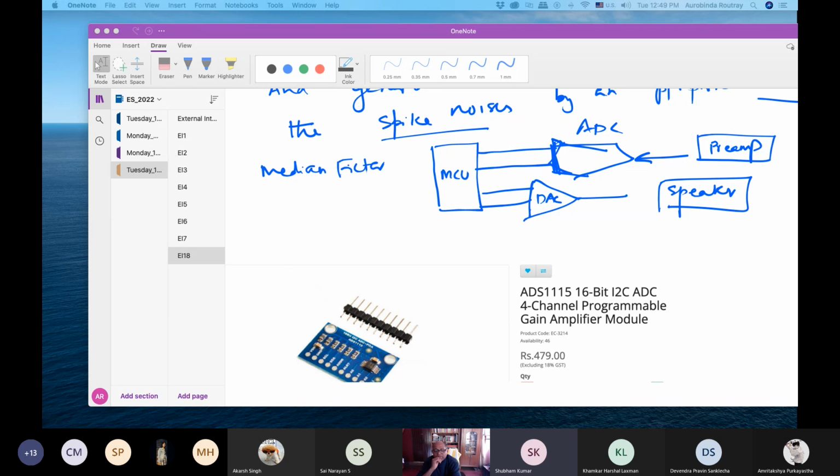If you don't use an interrupt, then you have to wait till the conversion is complete. You give a start conversion and wait until the conversion is complete, then bring it. So the conversion complete should be an interrupt. It will go to the subroutine to just get the ADC data and give another start of conversion.